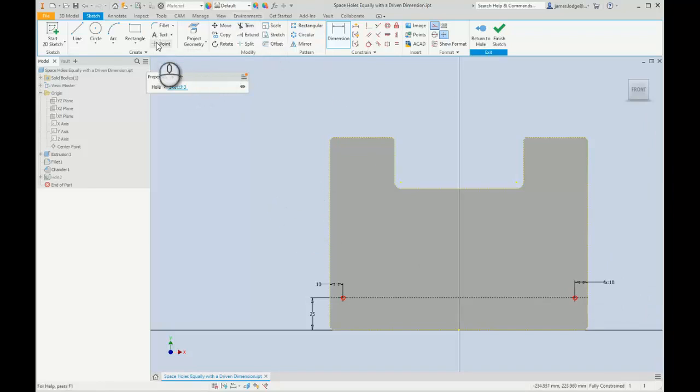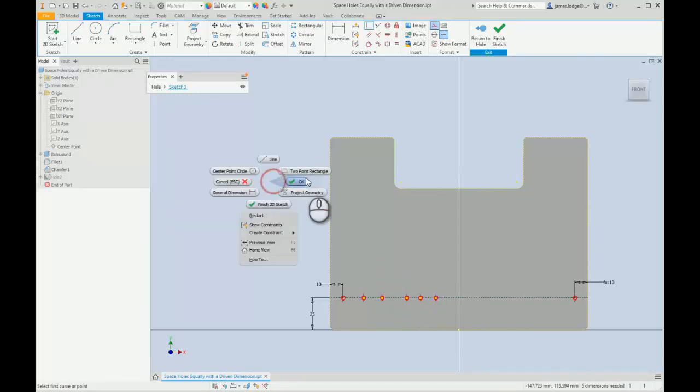I'm then going to select the point again, and this time I'm just going to place a couple of points along this specific line. Because I don't want it to end up using any of the tracking lines, I'm just going to hold control. I'm going to place a few points there. I'm then going to constrain them using the coincident constraint to ensure that they are attached to my construction line that I placed before, like so.